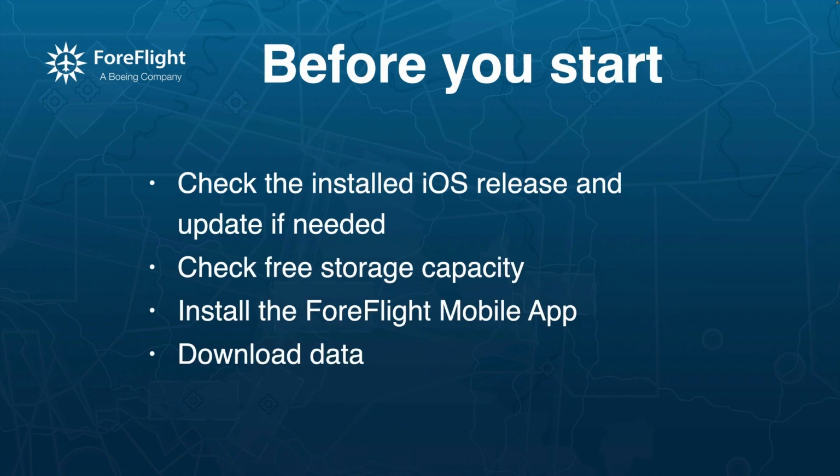Before installing the ForeFlight mobile app, check the installed iOS version and update if necessary. You should also check whether there is enough free storage space available. Then you can install the app, sign in and download the data.